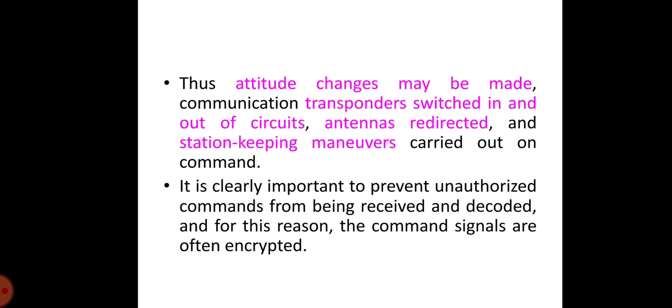Tracking of the satellite is accomplished by having the satellite transmit beacon signals which are received at the TTC Earth stations. Tracking is obviously important during the transfer and drift of the orbital phases of the satellite launch. Once it is on station, the position of the geostationary satellites will tend to be shifted as a result of the various disturbing forces. Therefore, it is necessary to be able to track the satellite's movement and send correction signals as required. Tracking beacons may be transmitted in the telemetry signals or by pilot carriers at frequencies in one of the main communication channels or by special tracking antennas.